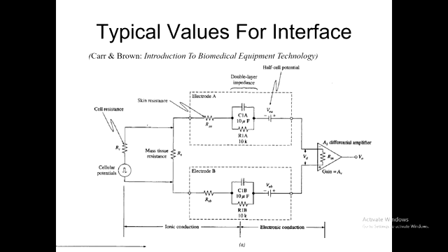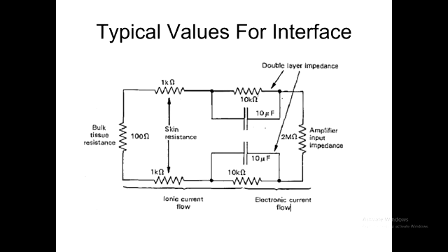Yep, just with the next slide. The next slide? Yeah. This one? Yeah. Where are the inputs and outputs? The inputs are actually going to be over here. It's not shown. What we're really doing here is we've got a dead circuit where the voltage sources that would normally be sitting in here have been regarded as short circuits for the sake of figuring out what the time constant would be.